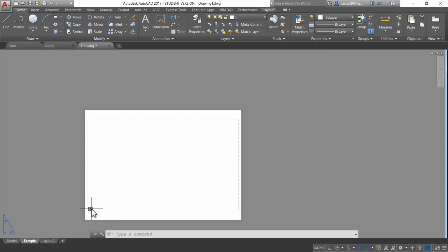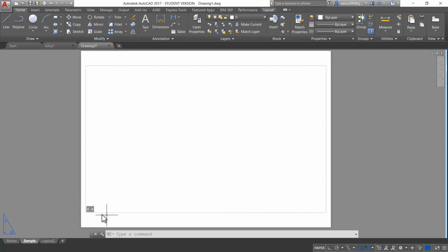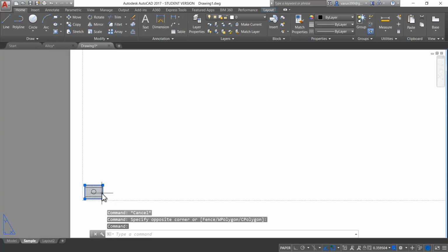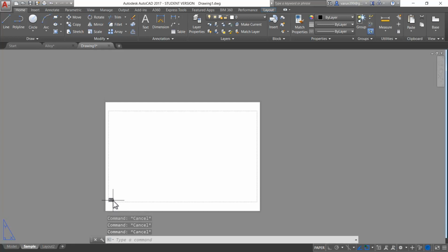As you can see here, our object has become very small. The boundary of this object, or the square which comprises this object, is known as the viewport, which we have discussed. So when you select this one, that viewport is selected now. Right. So that means that this viewport is at a scale of 1:1 to this sheet.